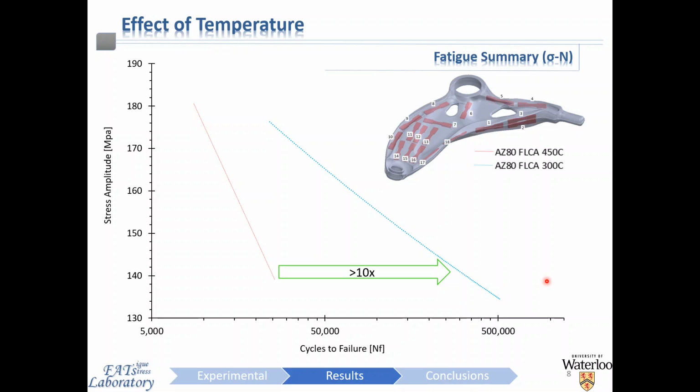Although we did look at a post-forging heat treatment in this particular project, I've chosen not to discuss them here as they're very alloy and application specific. So you can simply think of the analogy that the final heat treatment will govern the resulting microstructure, as it does in many materials that we utilize in engineering systems. The precipitate content is also governed by this final heat treatment, and the morphology of these precipitates, as well as the final properties. If no specific heat treatment is given, it's the last step of the thermal history during the forging process that effectively is replacing this heat treatment.